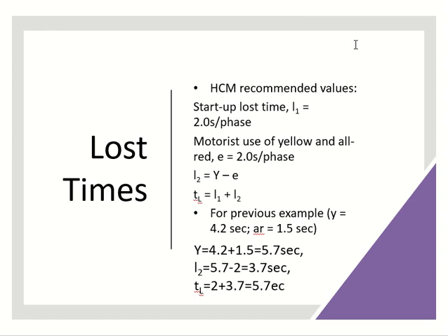Okay. So because of these vehicles, the clearance loss time is not actually this. It's actually 2 seconds after yellow. So my total time of yellow and all red is how much? 5.7. Out of this, in the first 2 seconds of yellow, people decide to go. So from 5.7 seconds, I will subtract 2.